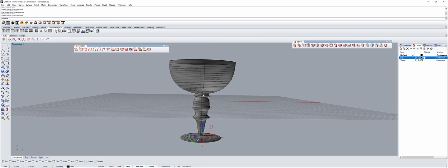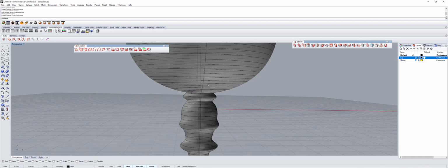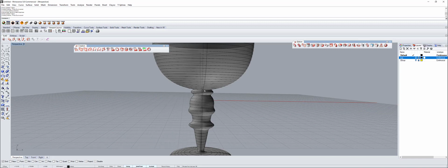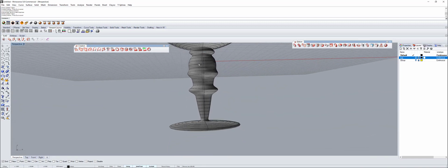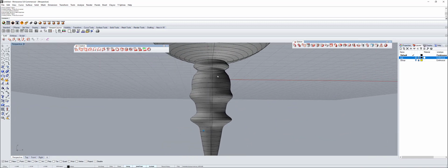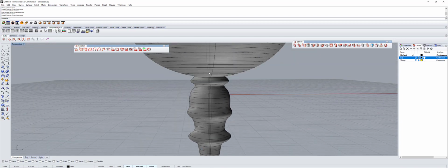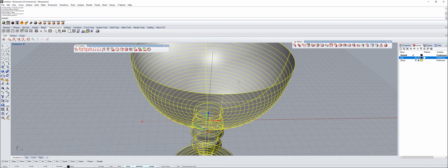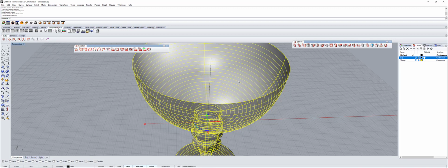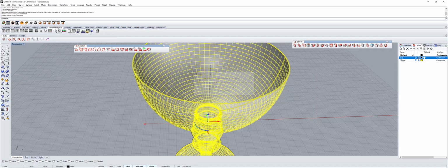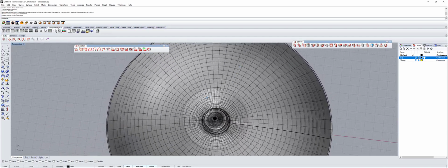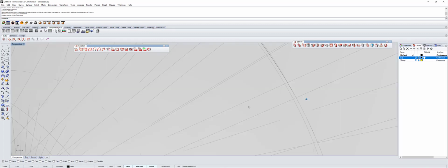Okay, so Houston, we've got a problem here, guys. Have you seen in the wine glass cups, this part of the crystal is completely solid? So if we do an offset command here for the surface, and I use the same 0.4 millimeters, enter. It's going to be just that little thickness, but it's going to be a hole all the way inside.